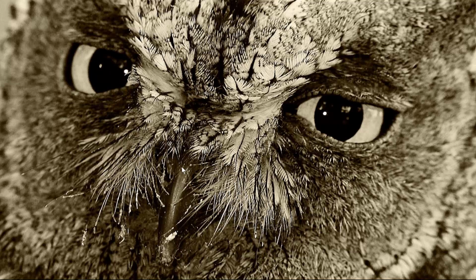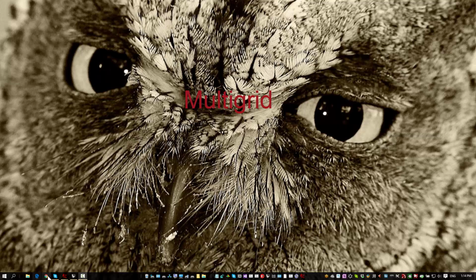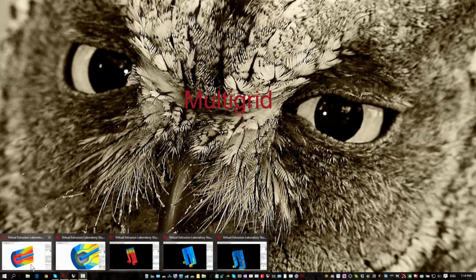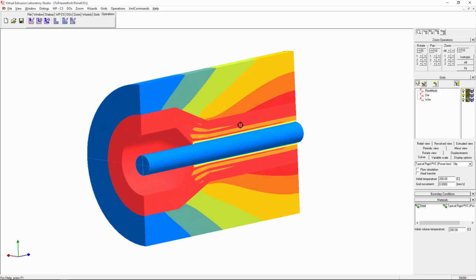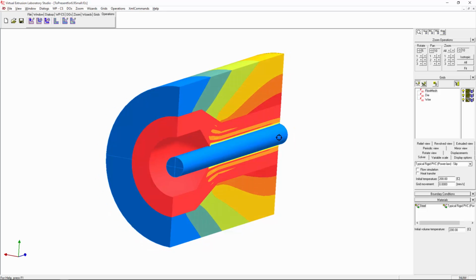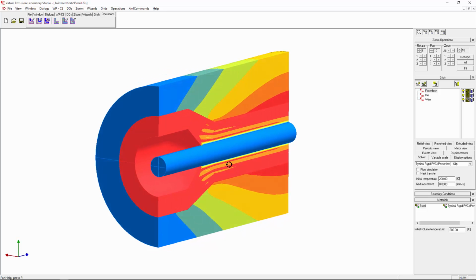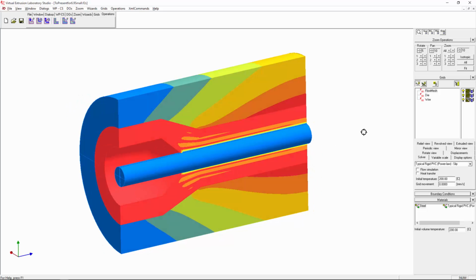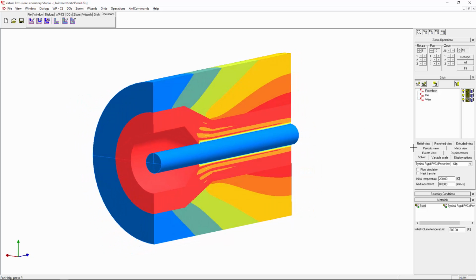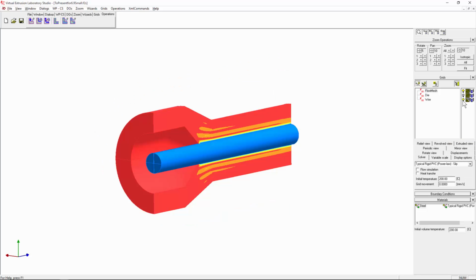This time I'd like to show you one of the main features of version 6.9, which is the multigrid option. It has been established already in 6.7 and 6.8, but now in 6.9 it really has become a standard, mainly due to some new set of boundary conditions which allow the multigrid to work much more efficiently. The idea came from simulating the steel as a part of the solution, because we of course can look at the flow mesh only.